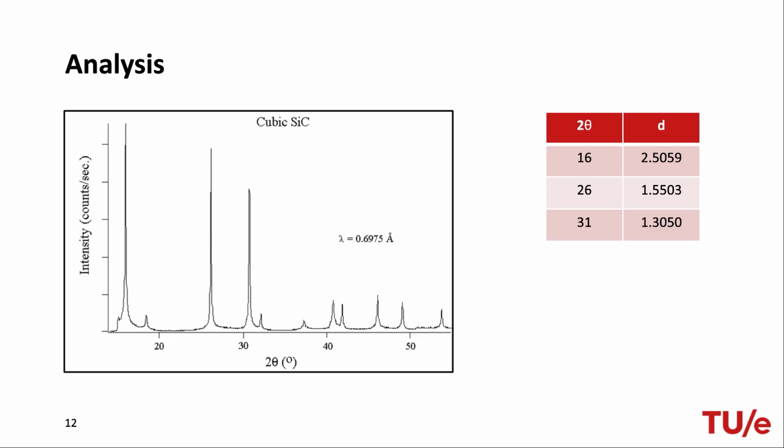The width of the peak should be measured by the width at 1/2 of the maximum intensity height. This is inversely proportional to the crystal size, which can be calculated by Scherrer's equation. Here, d is the crystal size, k is the Scherrer constant, and beta is the width at 1/2 maximum peak height. Therefore, a thinner peak equates to a larger crystal, while a broader peak can suggest smaller crystal size, amorphous character, or lattice imperfections.